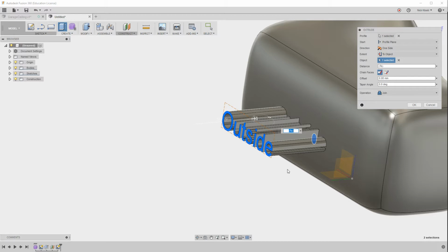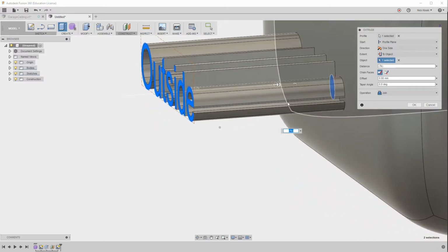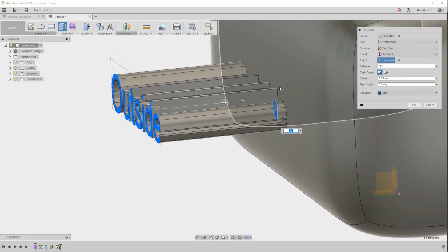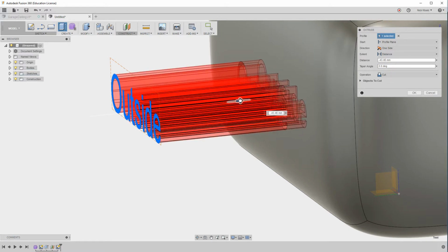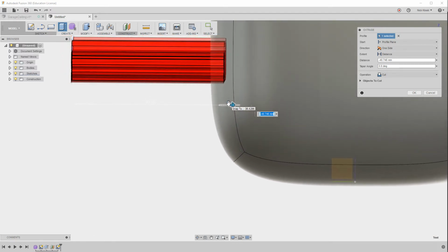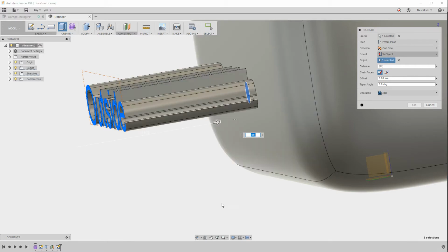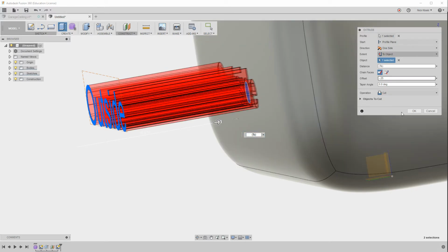And since it's going just to the face, you are creating it because it hasn't gone inside of the face yet, so you're not activating a cutting tool. If you actually drag it, you would actually start to cut, but you would be cutting at a flat termination plane. So what you can say is distance to, and then an offset of 0.25, or actually offset of negative 0.25, and say OK.